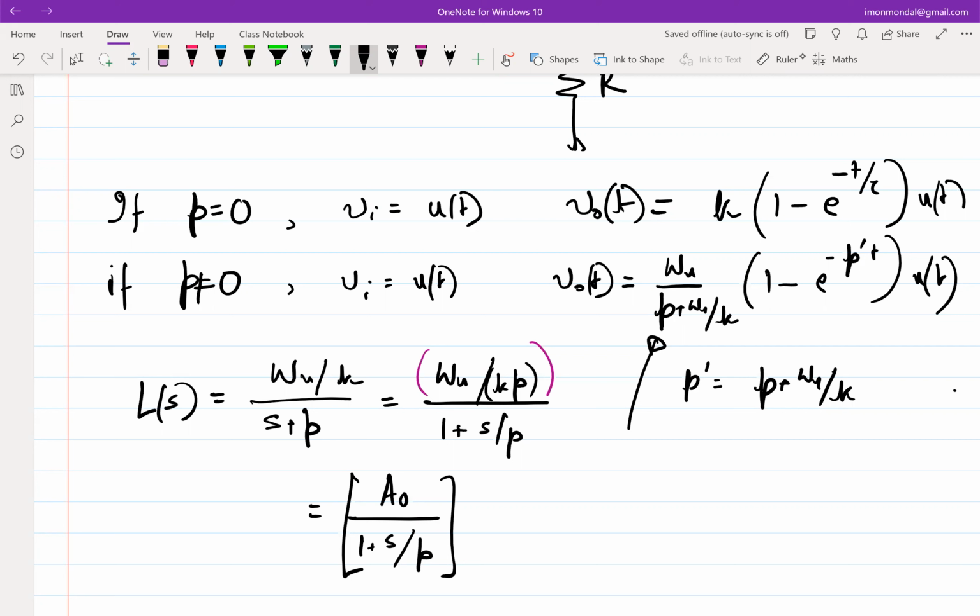Okay, so which essentially means that I need not necessarily fret about not having an ideal integrator. If I cannot get an ideal integrator and I still want some bandwidth of the closed loop system, then I should be satisfied with whatever I am getting, as long as the UGB of the open loop system is the bandwidth of the closed loop system. And I should not bother, because even if you have an ideal integrator, you will not get infinite gain at all frequencies. Even though we make a big deal about DC gain, you never achieve DC, because to achieve DC you have to wait for infinite time. So always you will have some error, as long as you are satisfied with whatever error you are getting.